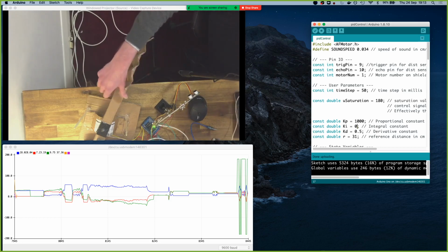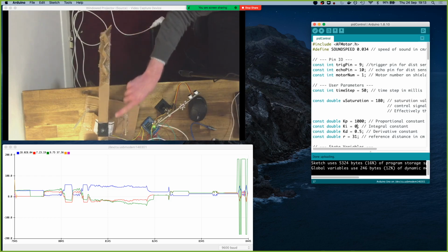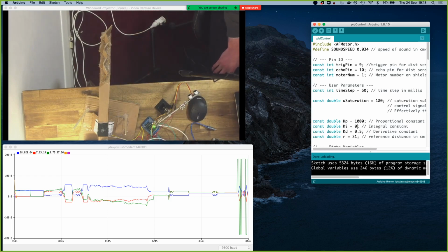If you don't want to go all the way into modeling this whole system with differential equations, that's when tuning methods such as Ziegler-Nichols, and a few others floating around, come into it. They're a little bit more involved. The Wikipedia article on PID control is actually quite good and in depth, so I'd recommend checking that out. Basically, with the Ziegler-Nichols method, you use proportional gain control and find the period of oscillation it starts oscillating at, and then there are rules for setting the different constants based on that period and what gain created those oscillations.